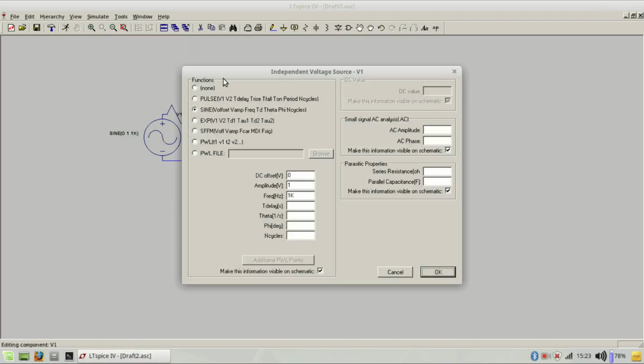Okay, if you right click there, you choose this pulse. Okay, and you want to specify the various parameters, initially 0, and just to retain the situation we had in our actual simulations, we will put the rise to be 3.